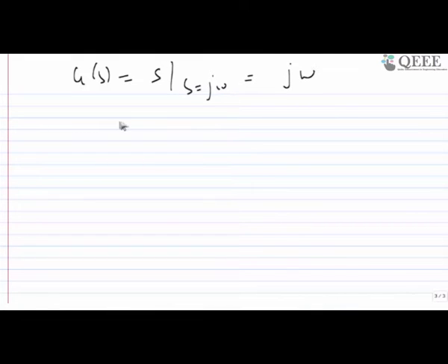If we compute the magnitude of G(j omega), you will get omega only, so it would be a straight line. But if you have a more complicated function, let's say omega square or omega cube, they would generally be smooth functions. Those functions also we can approximate by a straight line while plotting the Bode plot. This is what we're going to see in a couple of other slides.